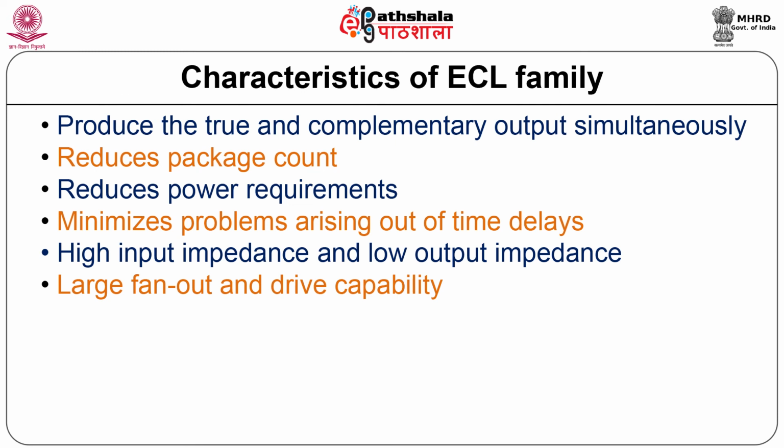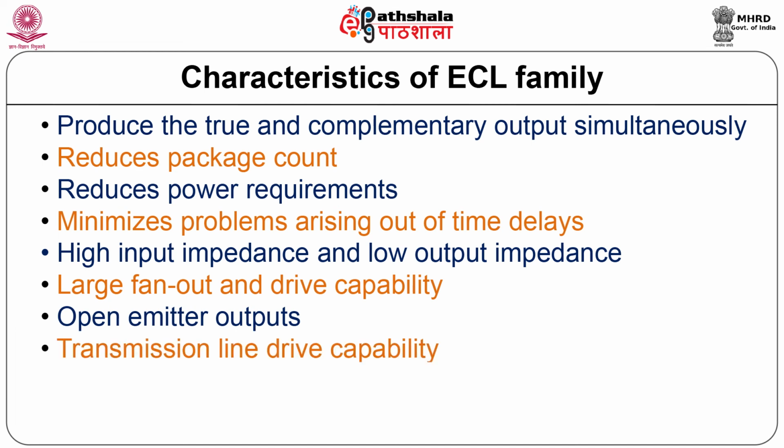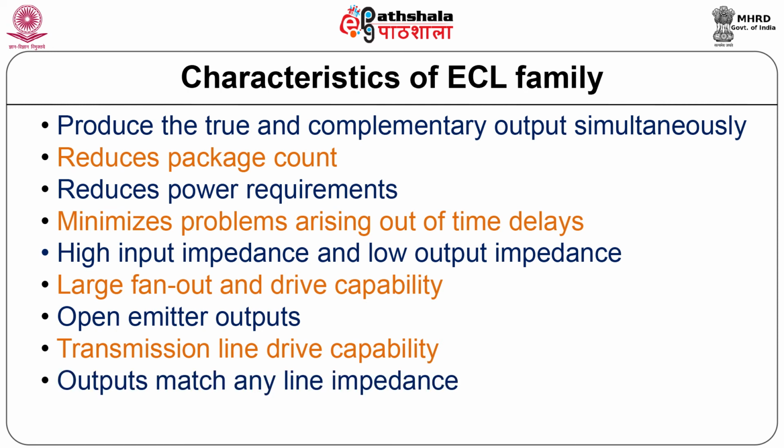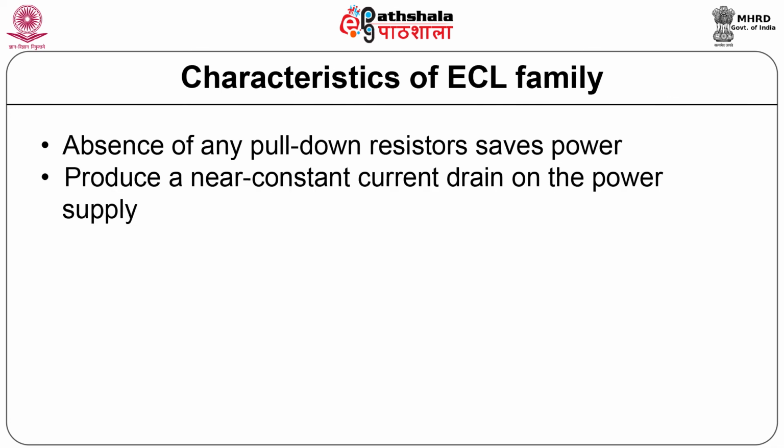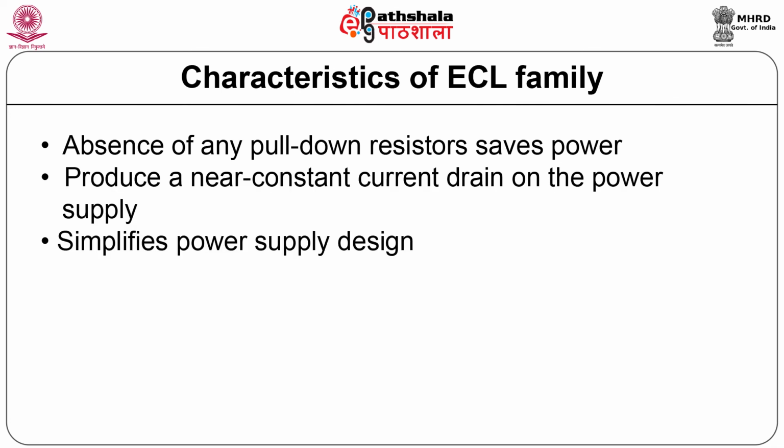ECL devices with open emitter outputs allow them to have transmission line drive capability. The outputs match any line impedance. Also, the absence of any pull down resistors saves power. ECL devices produce a near constant current drain on the power supply, which simplifies power supply design.